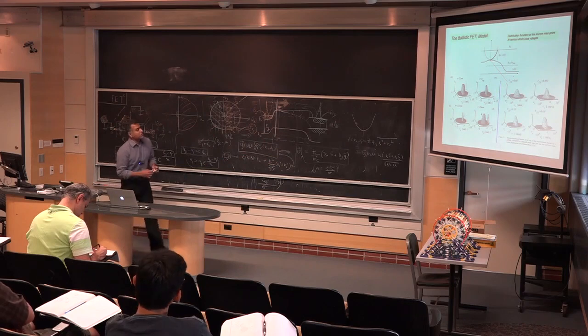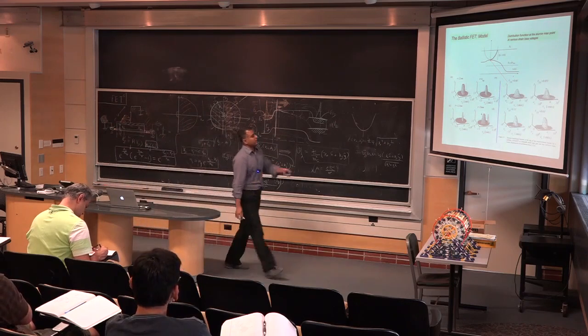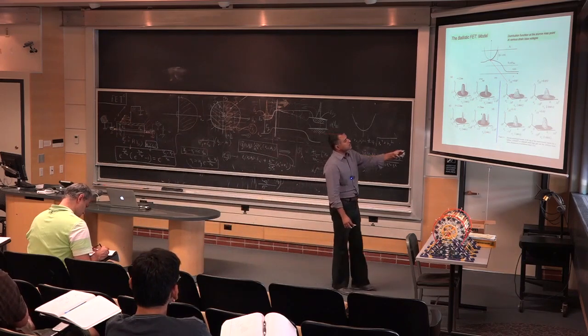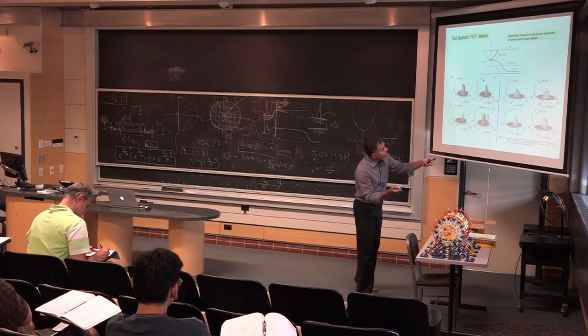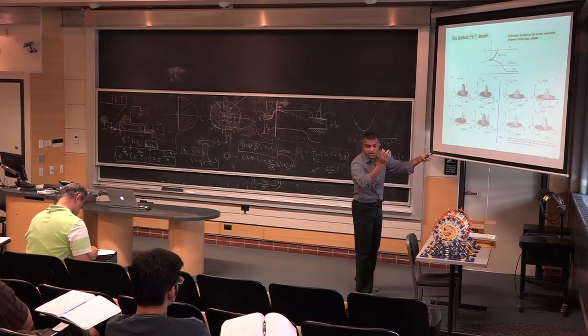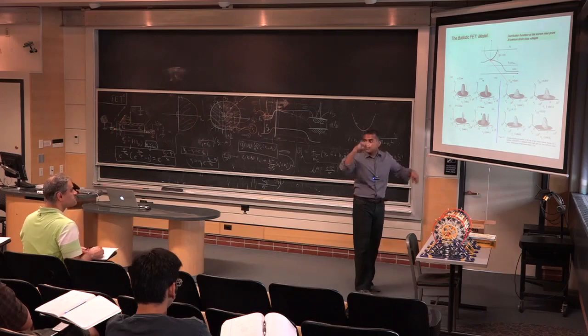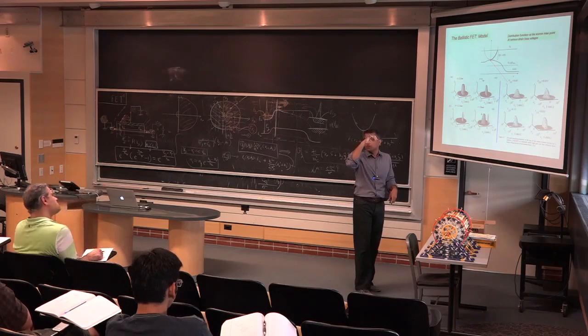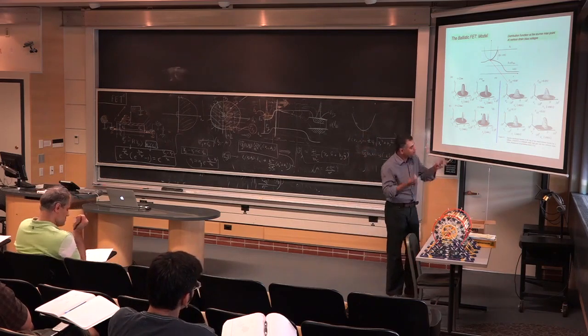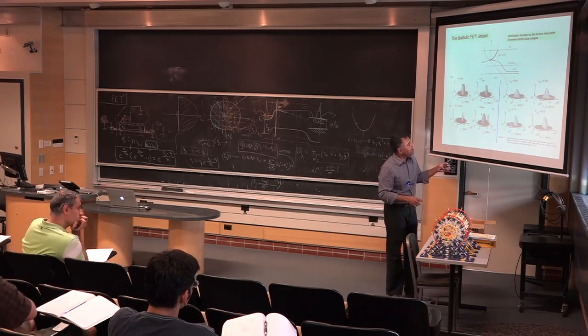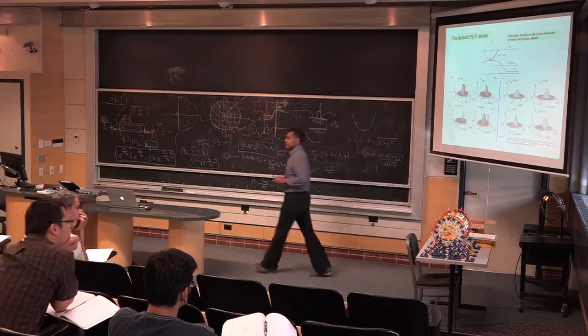There are quite a few more. When the drain voltage is 0, you have a symmetric distribution in k-space. You apply a little 50 millivolt drain voltage. You can see the right-going half has gone up now. The left-going half has gone down. But if you integrate the area, it's still the same, because the carrier density is not controlled by the drain or source, it's by the gate. So that's the key difference, and that is the heart of gain of the device, and all the things that are good about the transistor. You can kind of see all that stuff now.